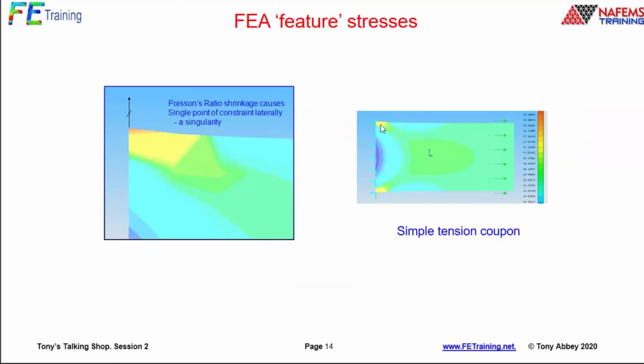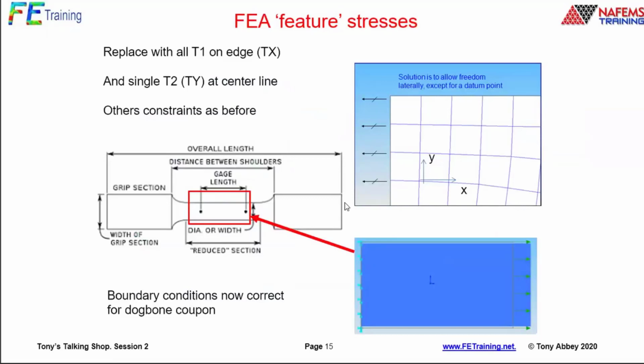Okay, I've done a bad modeling job there, but we talked about Saint-Venant's principle last week. Maybe I just say this is the area of interest. We're going to let that go, but I still want to explain it. I want to put in the report why that's occurring. The reason it is occurring is because I've done a very bad representation of the boundary condition.